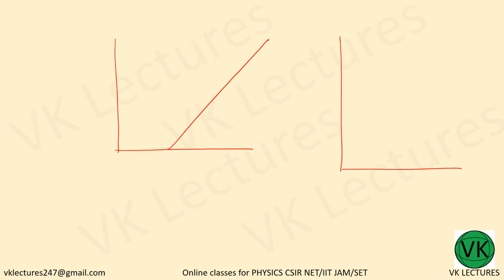Let us take this one. So this is called the piecewise linear model or approximate model. In that, this is called VB, the barrier voltage. The moment it passes the barrier voltage, you will have a current in the diode. Now I am dropping a perpendicular down.